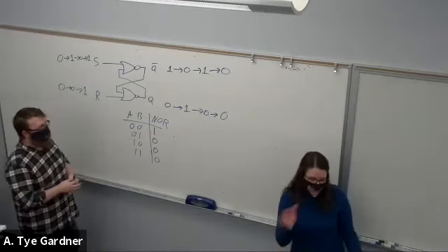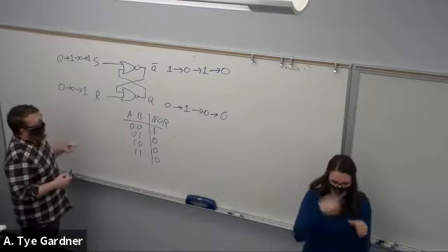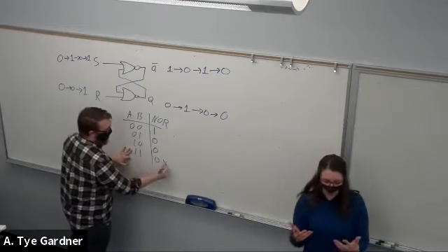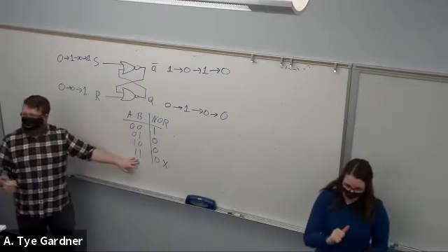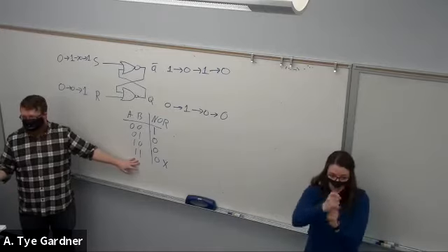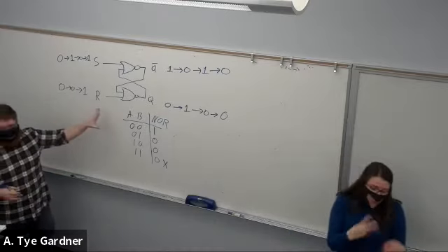And that's obviously a problem when we're trying to remember what it is, right? If we just don't know that definition, that's a problem. So we try not to ever do both set and reset in an SR latch. We avoid that because it causes problems. Now, in the real world, it would settle to something and everything is fine.